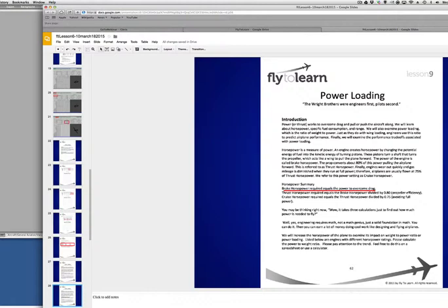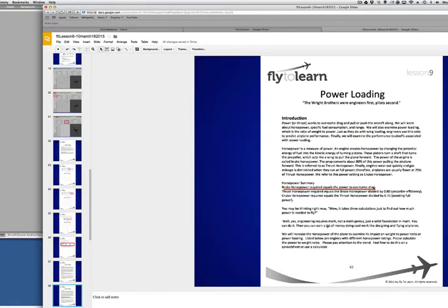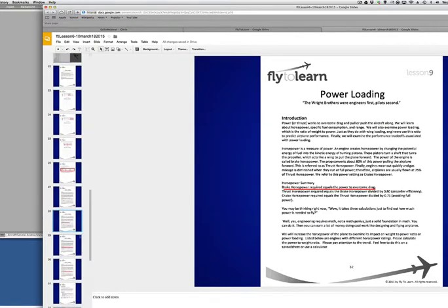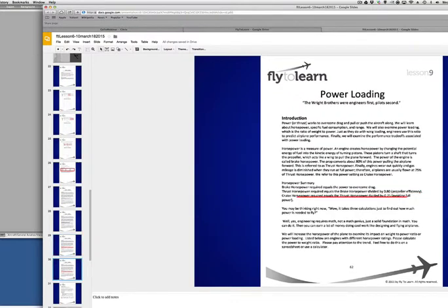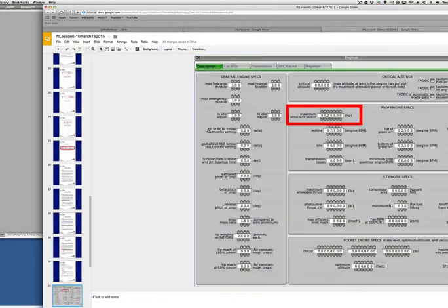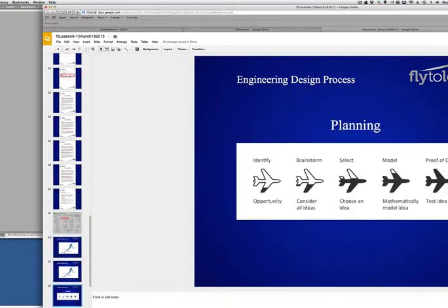I end up with about 166 horsepower, even though I only need 100 horsepower to overcome drag. There's inefficiencies in the system. And again, we just want the kids to start thinking about that. All right? So there's thrust horsepower divided by 80, divided by 0.75. We start getting into some questions there. There's maximum allowable horsepower on the prop. You can change that value.